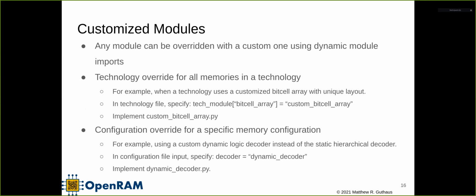Hey, Matt, this is Warren Nikolic from Berkeley. A quick question. When looking at Sky 130 produced layouts, we see perhaps a bit more use of a router than we would expect in a finished memory array. Usually, you expect memory arrays to be abutted, with almost no router used between the decoders, so the only thing we route is the supply voltage. Like we route the supply voltage, and actually there's also an escape router because in the OpenLane OpenROAD flow, you need pins on the outside on the perimeter. The escape router will route pins that are otherwise internal to the edge of the memory. Those are pretty much direct routes because there's not really any blockage.